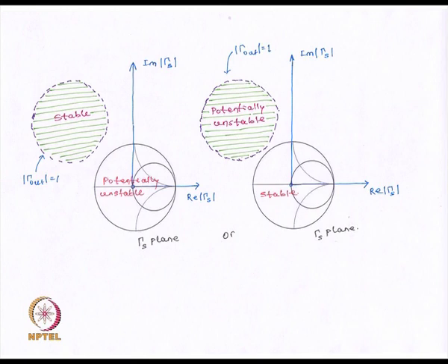Now, you might ask me here, we were talking about the stability circle being the boundary between stability and instability, then why are we discussing this Smith chart with its unit circle? The reason we are discussing it is because, in addition to modulus of gamma in and gamma out being lesser than 1, we also have to satisfy the condition that modulus of gamma S and gamma L should be lesser than 1. In other words, gamma S and gamma L should lie completely within the Smith chart of unit radius. So, that is also the condition that must be satisfied.